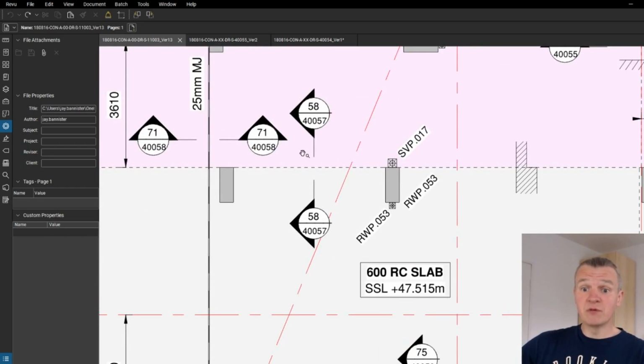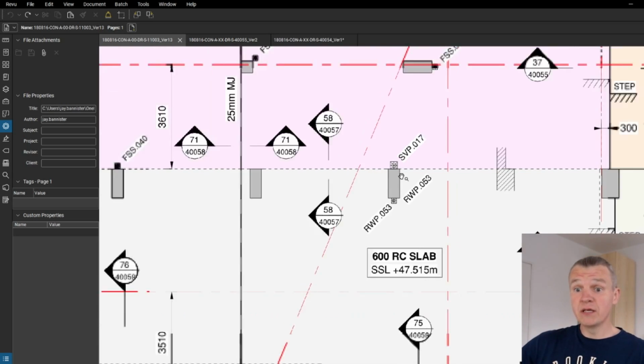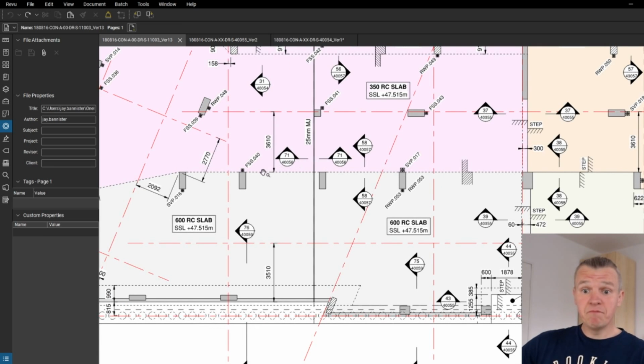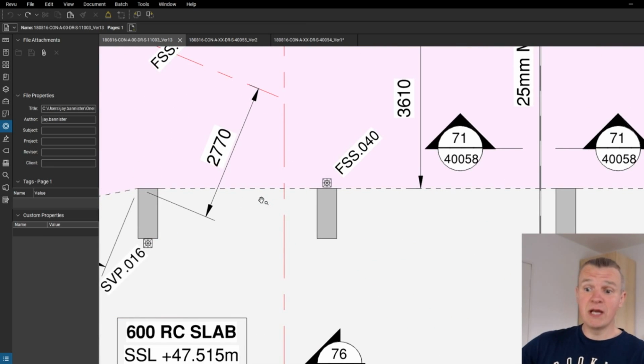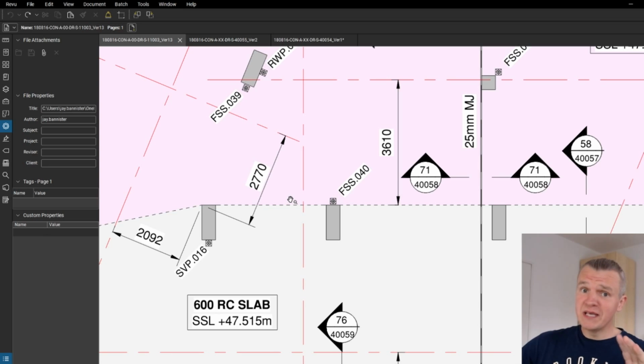That we're going to see here, there's a section, so we're going to have a look at a few sections as well, and the dashed line here showing the step. And maybe actually now I'm going to tell you about the dashed line, as the dashed line is actually called the hidden line as well. When you see the dashed line, that means the line is hidden by the slab here. So that means there is some step in the concrete. There's something that you cannot really see after the slab is poured, obviously, but there is something underneath.